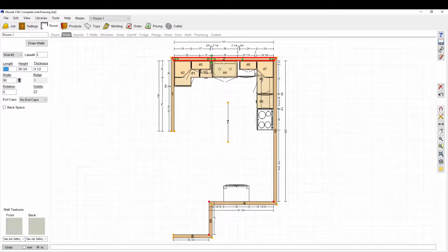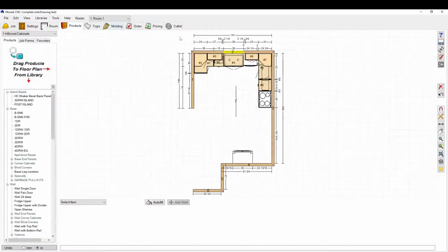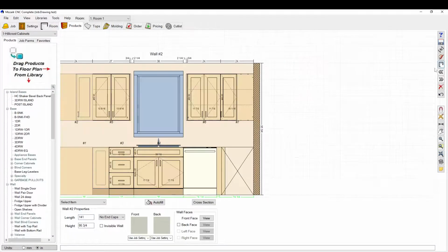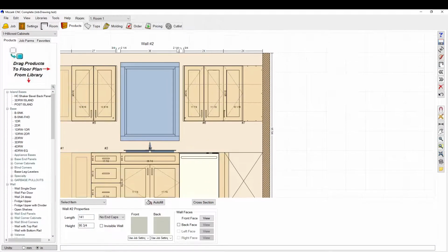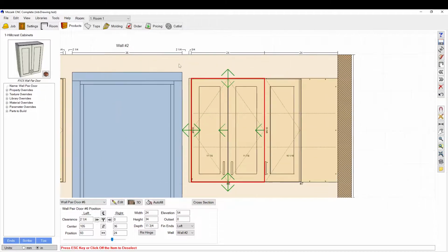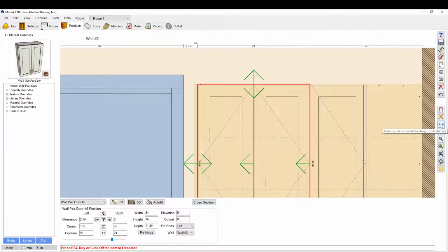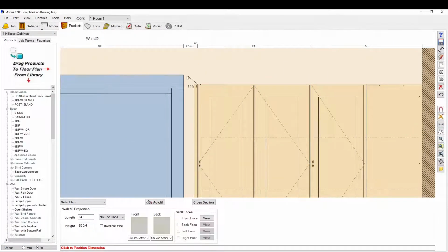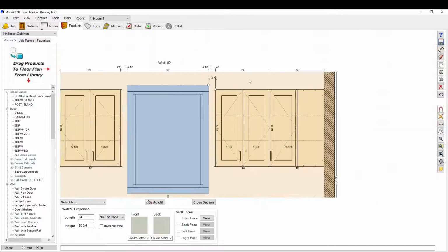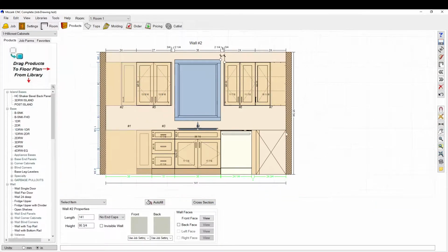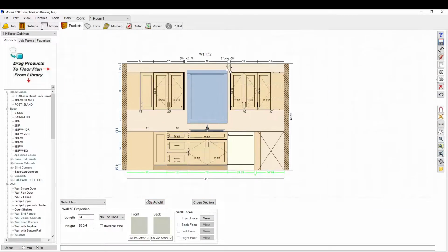In that menu, it does not account for applied panels, so keep that in mind. It's giving me 2 1/4, and then my 3/4 panel equals 3 inches. So my cabinet itself is 3 inches from the actual window, set by that setting in the main menu.